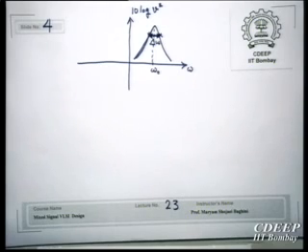reasons why, even if you have a ring oscillator, it doesn't always have the same delay at each cycle of oscillation. No physical system can be found whose performance is always the same at all timestamps. So effectively there are a lot of phenomena which change, and in each cycle you will see a small change in the frequency of the ring oscillator. How does it appear? It appears as a change in the edge of the signal. So the edge of the clock has some changes.